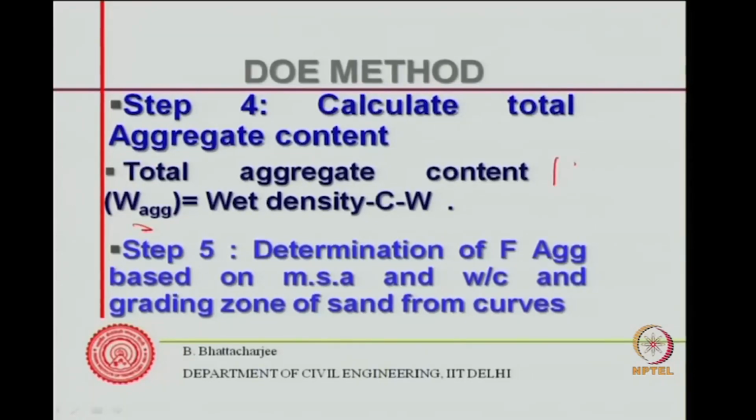In this particular case I was telling you, it would be 195 divided by 0.45 is C, and water is 195. So this would be 440.